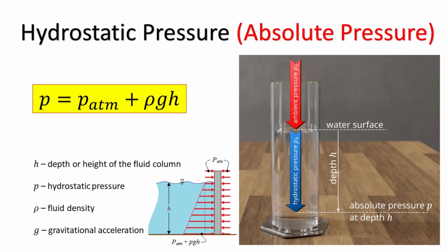If we establish a zero reference point for pressure, and we consider h as the difference in height of the liquid column between the testing location and the zero reference point for pressure, such as outer space, we can express the previous equation differently to determine the absolute pressure with respect to a vacuum. It is essential to emphasize that the density must remain constant in both equations. When dealing with a system containing two or more fluids of varying densities, any change in hydrostatic pressure must be addressed by dividing the fluid column into two or more distinct sections.